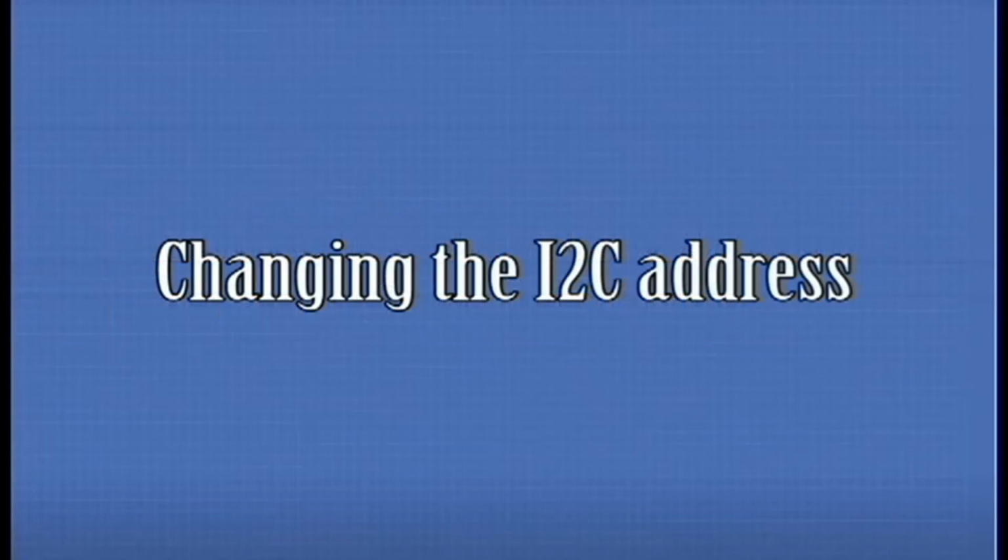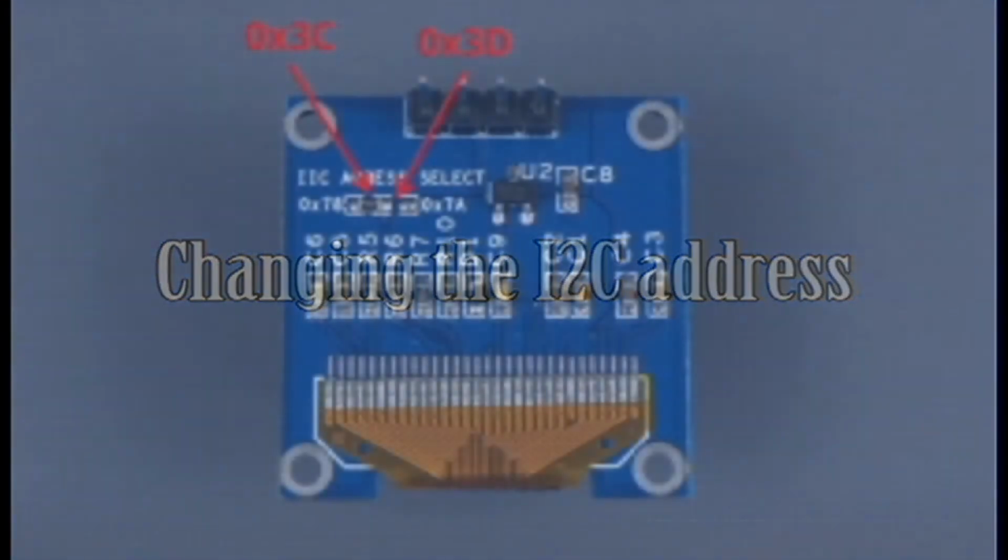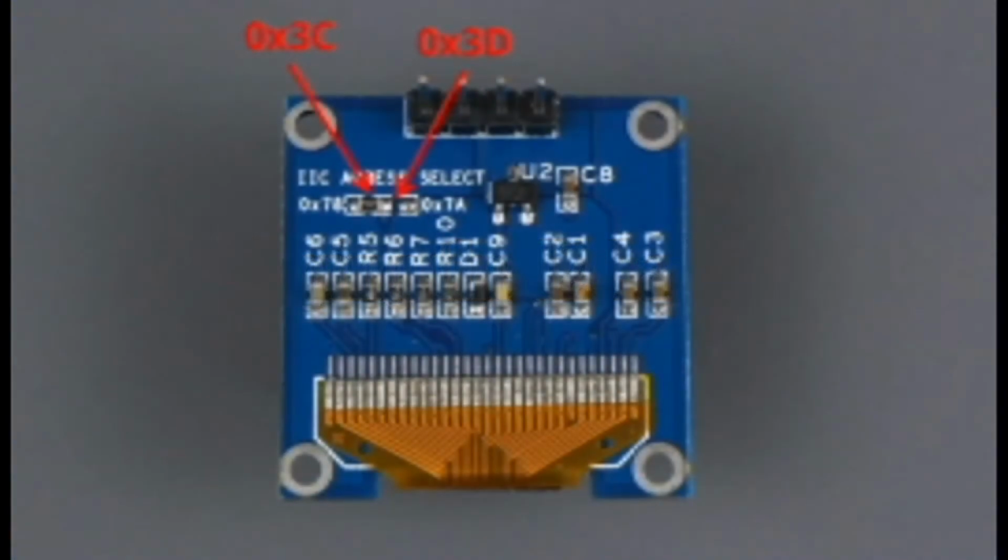Changing the I2C address. Many breakout boards have the option to change the I2C address depending on their circuitry. For example, take a look at this OLED display. By placing the resistor on one side or the other, you can select different I2C addresses. This also happens with other components.